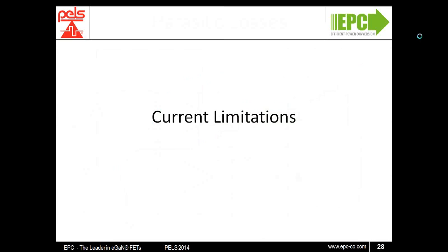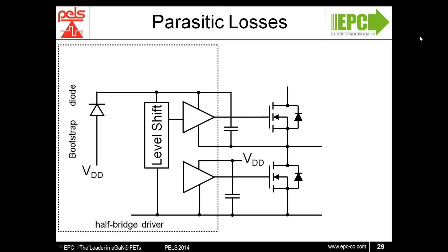So here we have a schematic diagram of 2 devices with a representative substructure of the level shifter gate drive that drives both devices. We can see that when you have a rising switch node edge, when the high side device is turning on, there is a capacitive current that flows through the bootstrap capacitor and charges up the internal IC well capacitance.